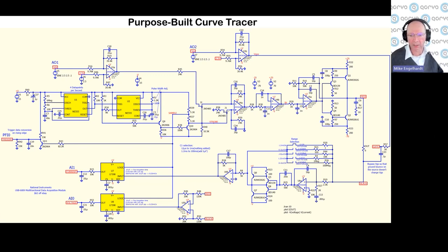And so what I did is I put in this other transistor. See, this transistor here, whether it's on or off, it's still ground, but it injects the same amount of charge into the same network, so it cancels the charge injection from that. It's kind of clever, and I haven't seen it before, but it gives me a nice clean square step wave here.